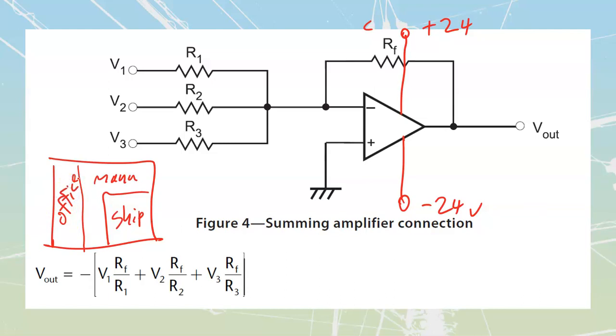Let's say that we've only got a single rooftop unit for that. Inside each of these areas, we're going to have a temperature probe, and those temperature probes are just going to be RTDs. What I don't want to do is base all of my building's heat on what's inside of shipping. I still need to make sure it's decent inside of shipping, but it's not going to have to run the whole building because they're going to have those big doors open and closed all the time.